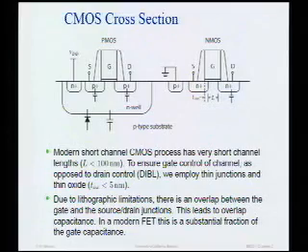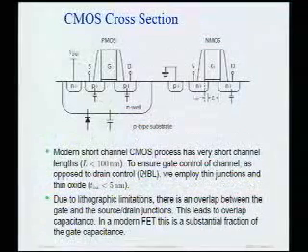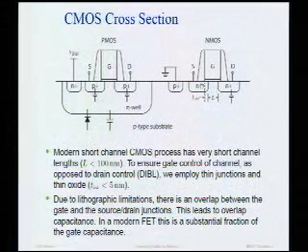But there are other effects. There's the so-called DIBL, or drain-induced barrier lowering. This has to do with the fact that if I make this drain voltage large enough, I lower the barrier for injecting electrons into this device. That also changes the threshold of the device, and it also increases the current. So in this class, we're going to be dealing with short channel transistors, so we have to be aware of these issues.